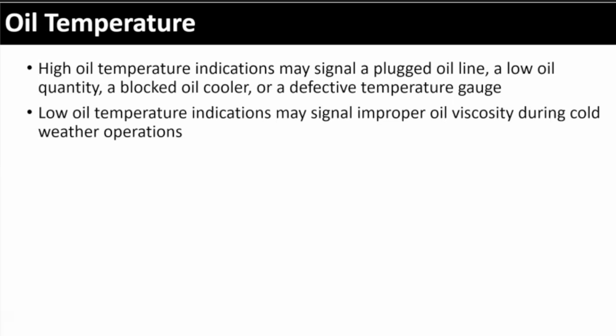Again, if you're at a high steep climb rate, what's your oil temperature indication going to be? It's like your cylinder head temperature. If you don't have that cooling, what's it going to do? It's going to get hot. You're going to see a high oil temperature reading. Again, lower the nose, continue your climb to get that circulation. Let the oil temperature and the cylinder head temperature come down.